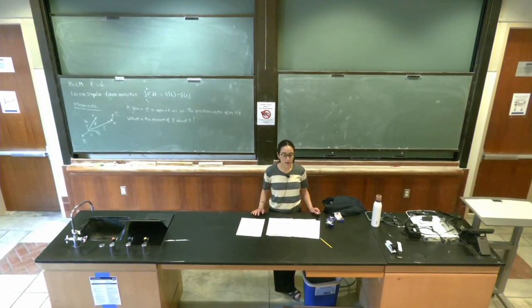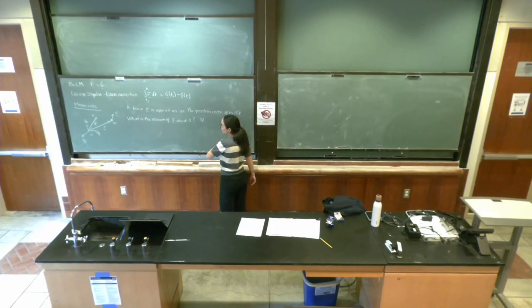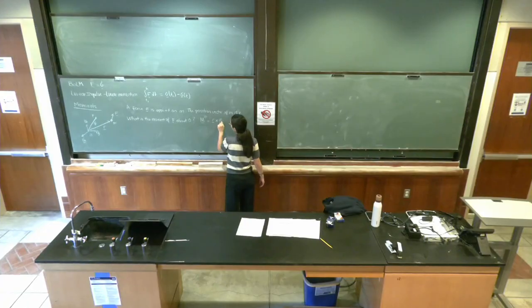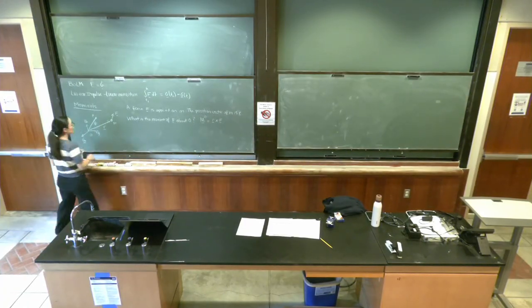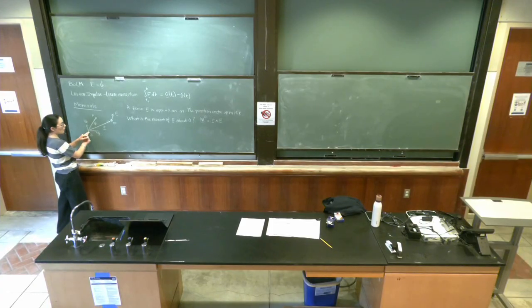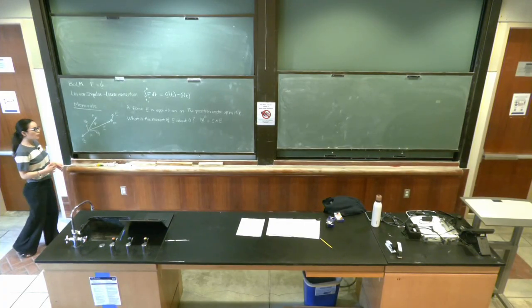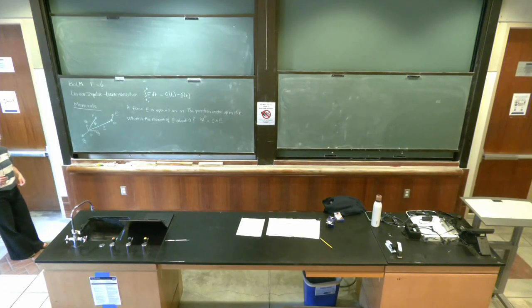Let me ask you this. Is the moment of a force a scalar or a vector? It's a vector, right? So it should be a cross product. So the moment of the force F about O is equal to r cross F. The position vector, so I'm trying to calculate the moment of the force F about this point O. It's going to be the position vector from O to the force crossed with the force, which in magnitude is going to give you the perpendicular distance between O and the force times the force. Now, do you remember this? Any questions about this?